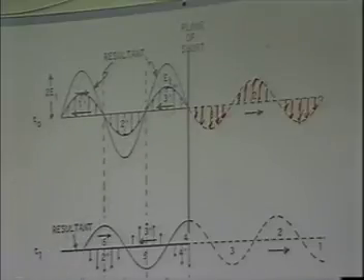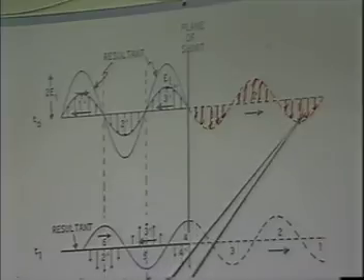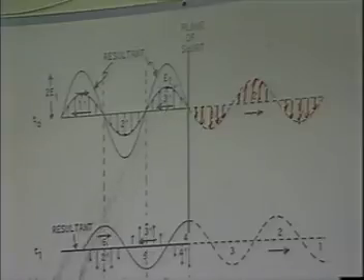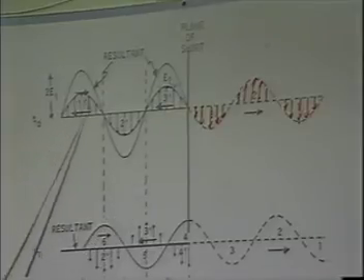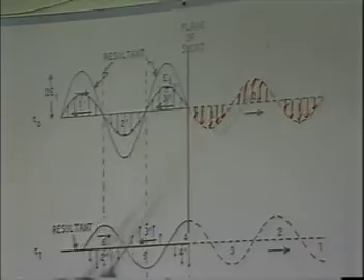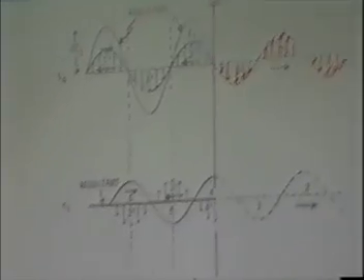If you could stop and see the overall waveform that exists, that's what's on the line at this particular instant in time. It should be very clear that's what's happening. This wave is traveling to the right at the speed of light. This one would have gone out here, but instead it's going back here. At this point in time, if you stop, this overall envelope exactly matches this folded over here, this folded over here, and this folded up here, such that when you take the resultant, you have this waveform.